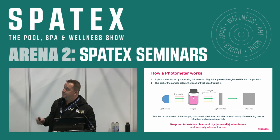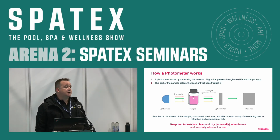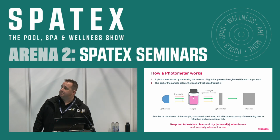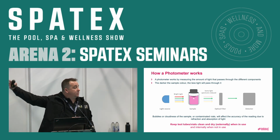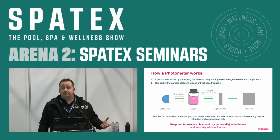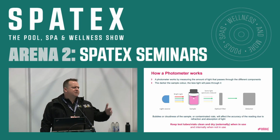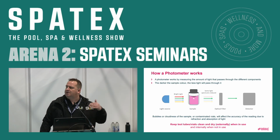So how does the photometer work then? It simply shines a beam of light through a cell, and uses a receptor to measure the colour, like we already said. It's the colour that it's measuring, not the chemistry. This is why we need to make sure the cell chamber on the unit is nice and clean, so we don't get any kind of contaminants. Even a good thumbprint on the side of a cell can throw the machine off a little bit. When we look at water testing, it's always consistency. Consistency is key: doing the right thing the same time every time.